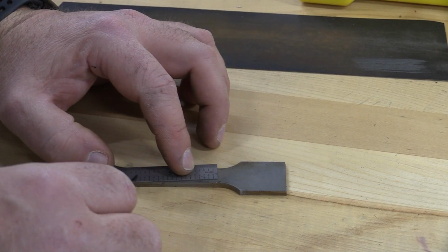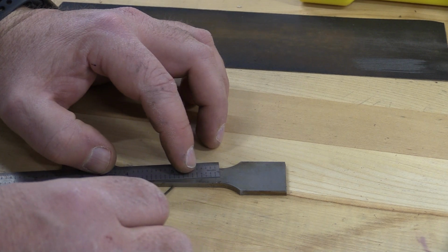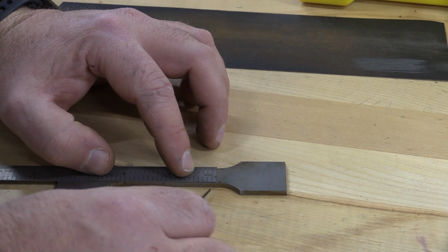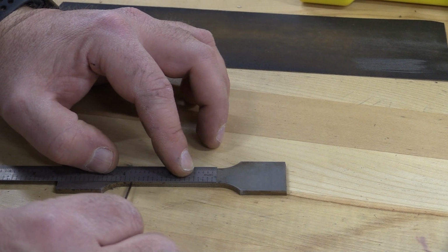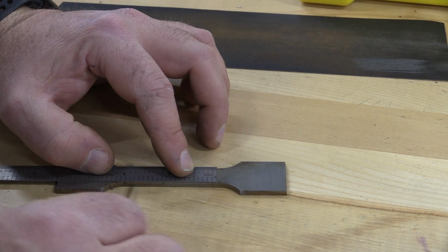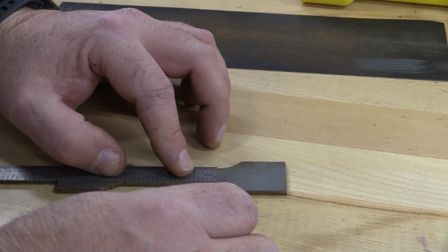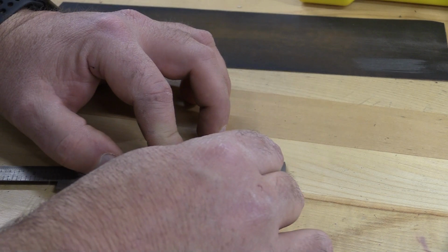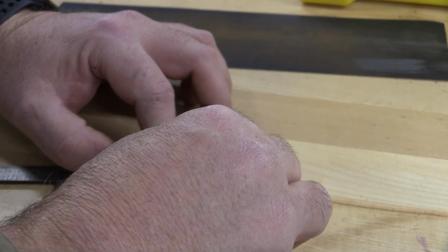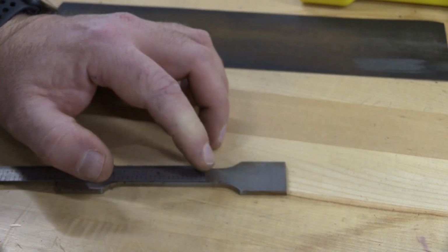Now what I'm going to do is make sure the scale itself is going to be parallel to this surface on the part. And I also want to check and make sure that the radius, I'm at the tangent point, that I can get the 2-inch gauge length between the two tangent points of that sample, which is really close. So I'm basically there, and then what I'm going to do is with this screwdriver, it's really sharp, we sharpened it up, I'm going to come in and scribe that line right there on the sample.